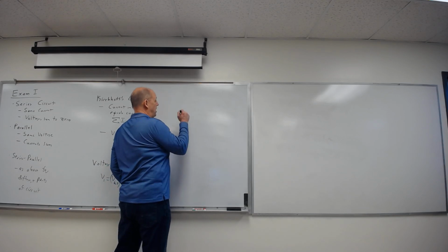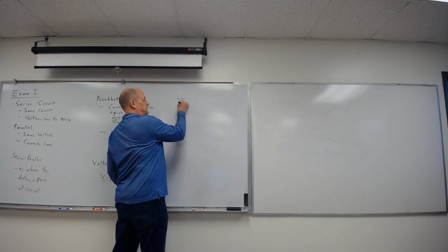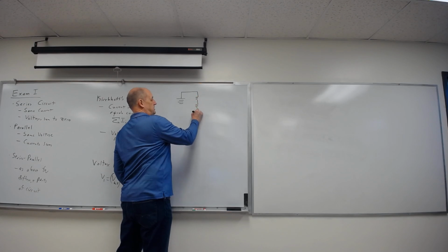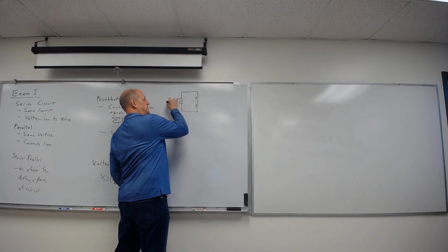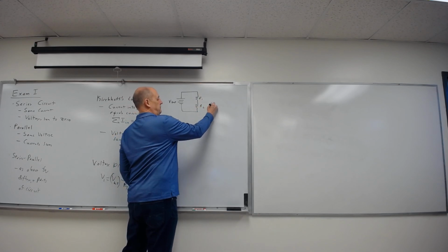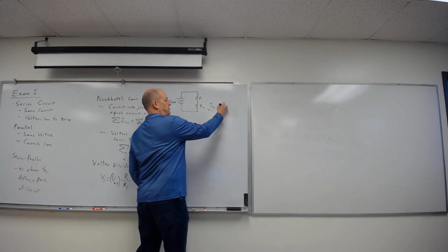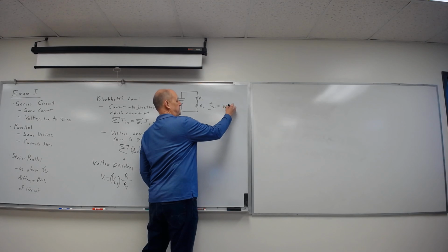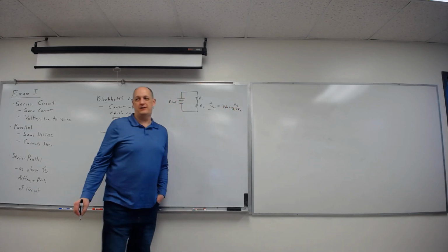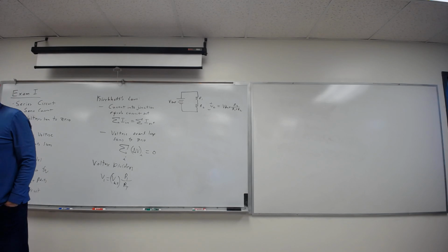So we have a couple problems we're going to work with this. One is, actually, there's several, I guess. Is we just have 2 resistors. The voltage here is just straightforward. Battery times R2 over R1 plus R2. So you should be able to handle that.